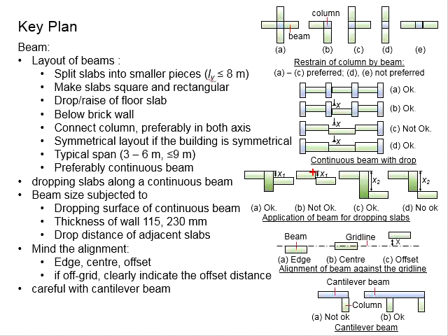You don't have sufficient areas to ensure these two slabs are in one piece. Sometimes there is a discontinuity, with directly no regions of contact. That means there is going to be a structural concern. To overcome this, you may apply a crossing beam here.